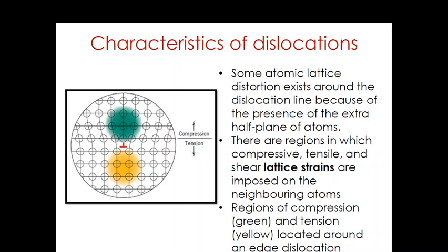When metals are plastically deformed, some fraction of the deformation energy, approximately 5%, is retained internally. The remainder is dissipated as heat. The major portion of this stored energy is strain energy associated with dislocations.